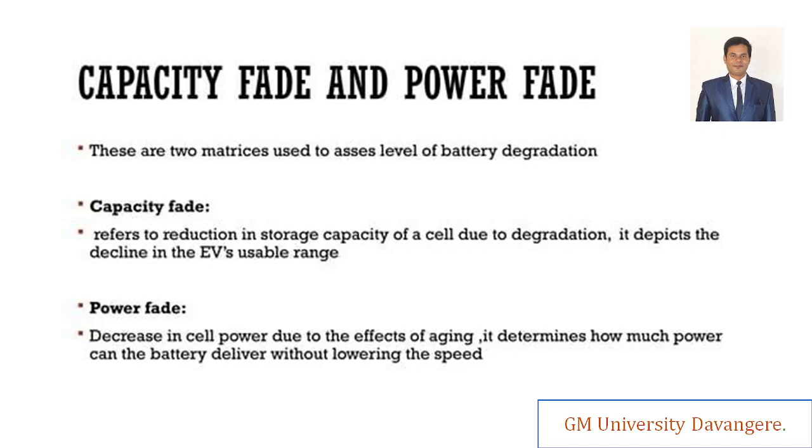Sometimes you plug your EV into the socket, right? Then you leave it for a very long time. So what will happen? It gets overcharged. The temperature may rise. Yes, after 100% also it is getting overcharged and the temperature may rise. So due to the rise in the temperature, the degradation will also happen. Due to the chemical factors, the chemistry also, the degradation will happen. Due to electrode failure, the degradation may happen. There are many reasons why degradation comes into the picture, right? We have to maintain the battery life. So you have to charge properly, you have to discharge properly, or else we are not expecting those aged cells in the EV, because it is not providing 300 kilometers. It is providing only 150 kilometers, which is half of the earlier range.